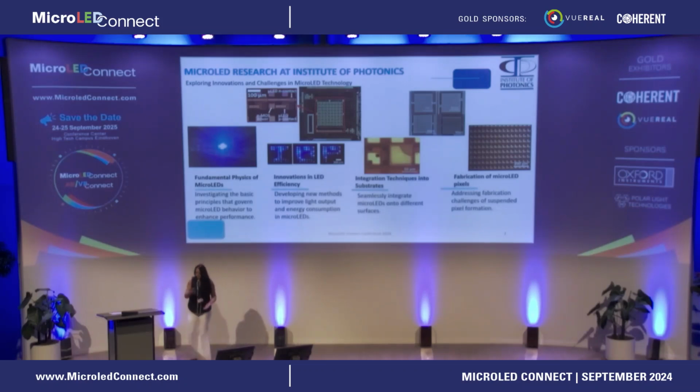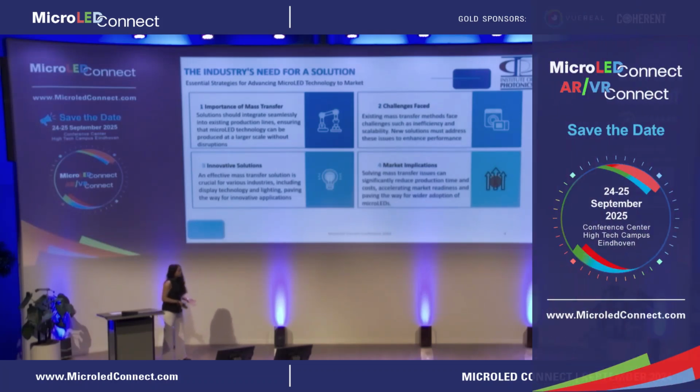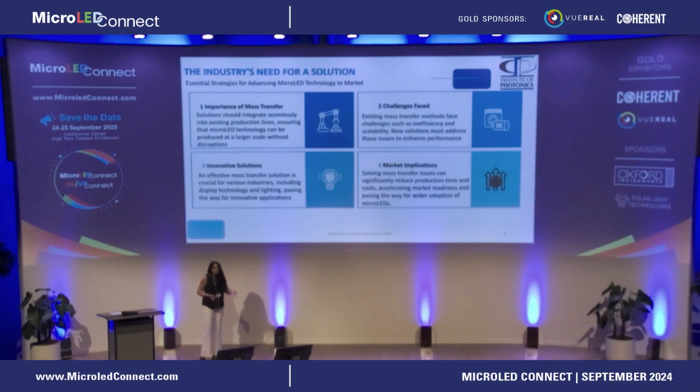So, all of this is great, and it works for the purpose of the research environment, when we want to pick individual devices and place them in functional photonic systems. It works fine. But then the challenge that we have, alongside the wider industry, is how we can actually scale this up. For micro-LED displays, we are talking about millions of devices, each, depending on the application, let's say on average 20 micrometers in size, that need to be pitch matched to the electronics that they are printed to.